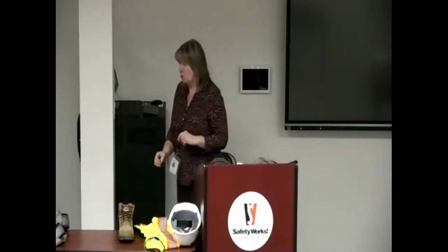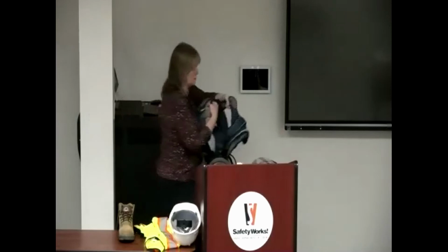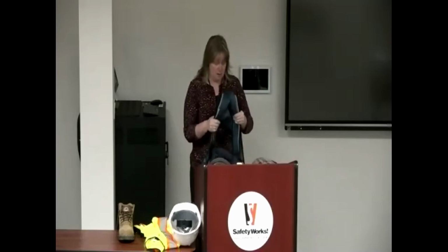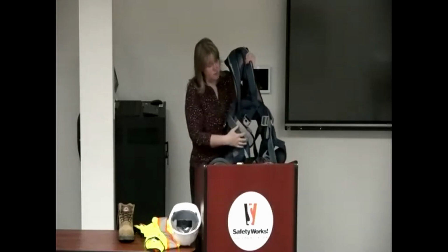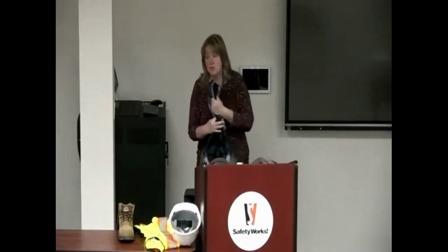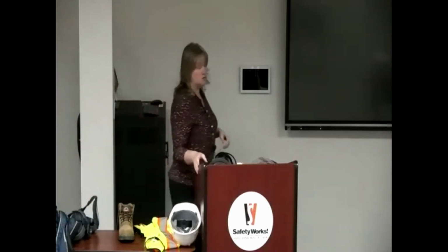Fall protection. When we have heights in our workplace, you may be required to wear fall protection. If you're in general industry over 4 feet, you need fall protection, whether it's nets or guards such as handrail, toe board, and midrail. Or if they can't provide that protection, you may have to wear fall protection such as a harness with lanyards, etc. A lot of training is required to use these, and these are very important to be inspected prior to every single use to make sure that you're protected in the event of a fall.